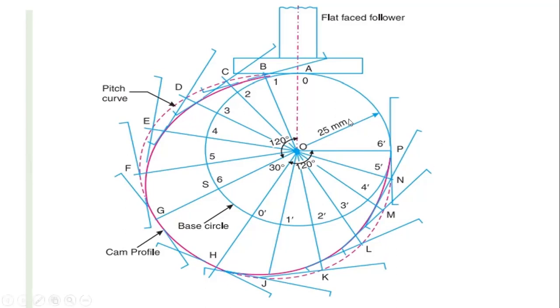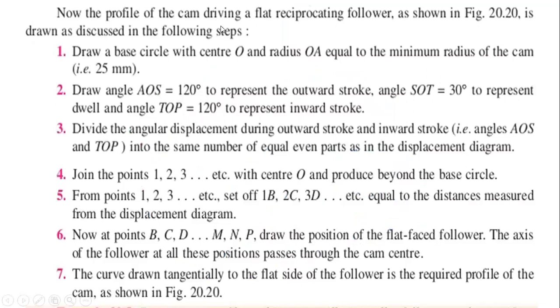Then draw the cam profile with a thick line using an HB pencil. So this is the procedure for drawing this profile. That is the only question they have asked in this model: to draw the profile of the cam.